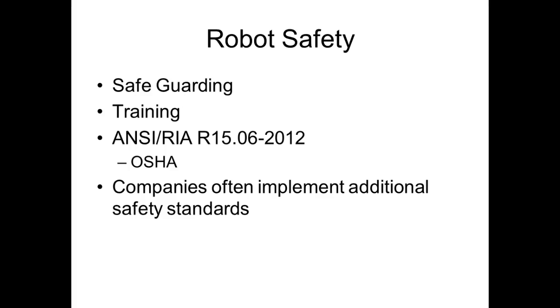Safeguards around the robot. Now, normally the safeguards don't come into play when you're teaching or jogging the robot. Everybody understand that? Safeguarding comes into play when you switch the robot to automatic. You switch that circuit to automatic and run that program, it is automatic, right? It will repeat that program.